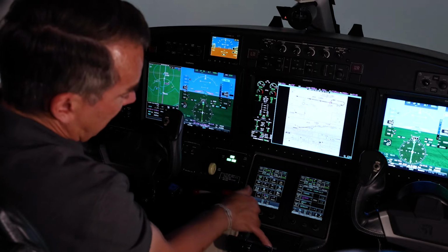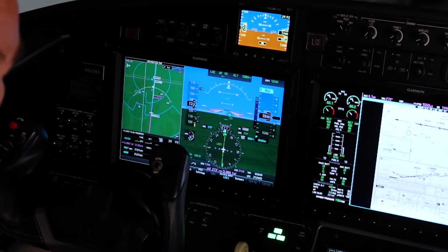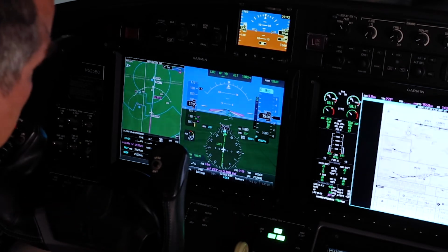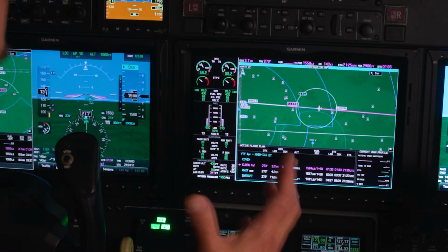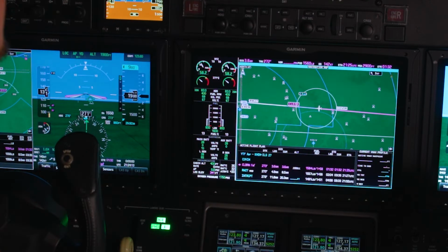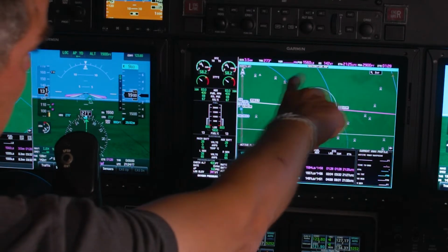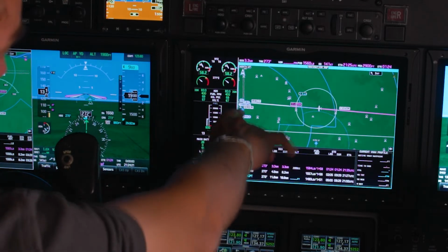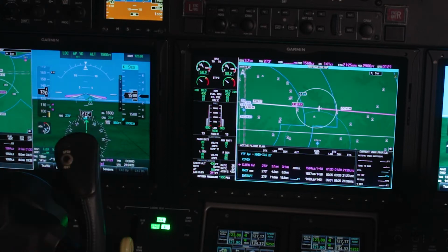We have our gear down, our flaps are at the 15 degree or takeoff and approach setting, and we're tracking a speed of about 130 knots. That puts us squarely in category C. On our map, this is an expanded protected area approach. So what that means is as category C, we have a minimum of 2.7 nautical miles of protected area. So we can put our range scale here to 2.5 miles. As long as any part of any of the runways sits inside that ring, we are in the protected airspace when we're at MDA.